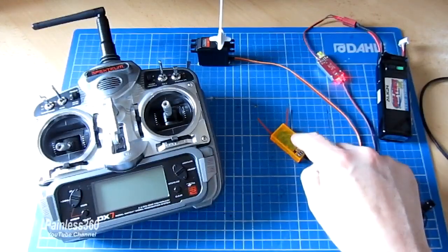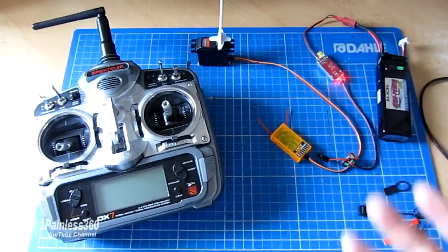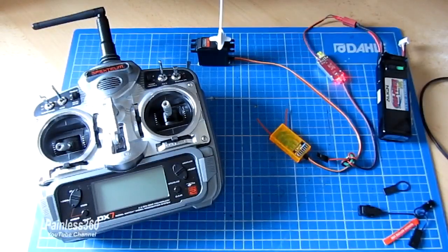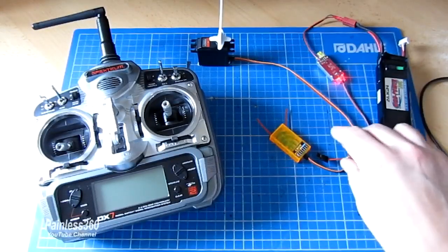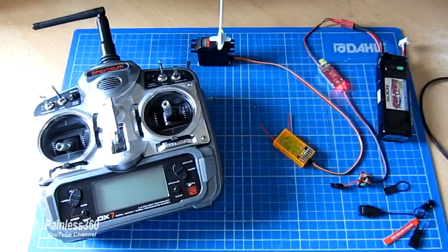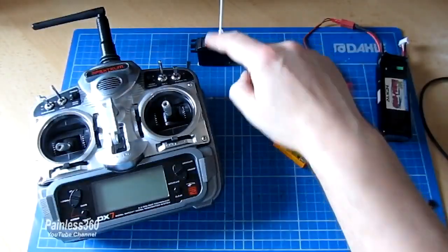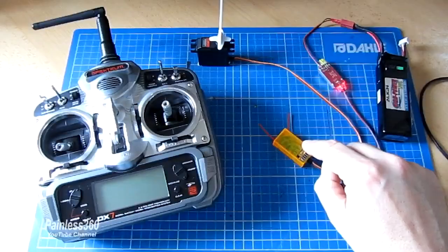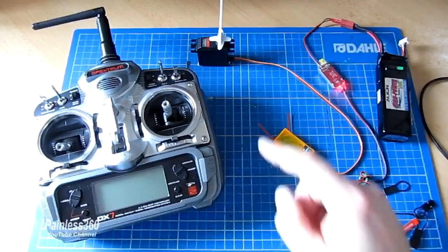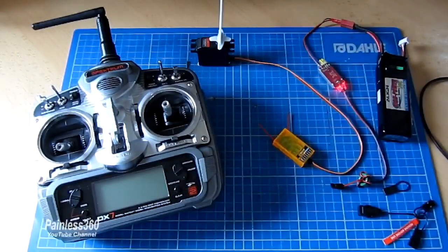Or send a specific level out so that the flight control board in a multicopter can realise there's something wrong with the radio and take appropriate action. Now, as you saw, nothing happened to the servo before, because the mid position where the stick was at was the position that was saved when the bind happened. But watch what happened if I bind it with the stick in a different position.